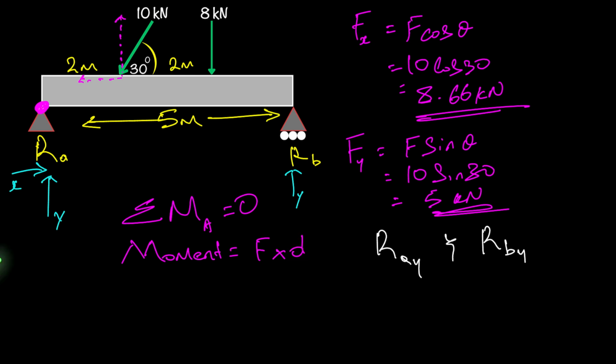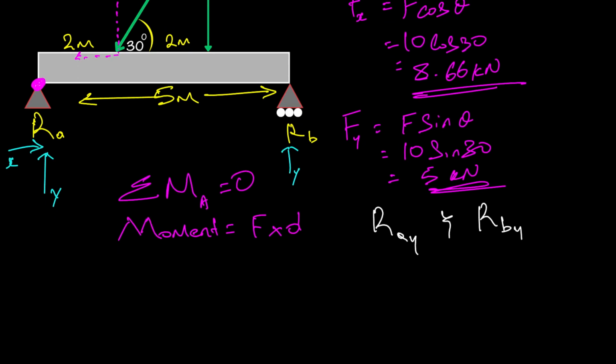Now, in the past, I've shown you how to do this using the system clockwise moment equals counterclockwise moment. I'm going to use a different method this time just to give you some variety, but it's going to work out to give the same working anyway, and it's good to introduce some new elements. So I'm going to take counterclockwise moment as positive, and clockwise moment as negative.